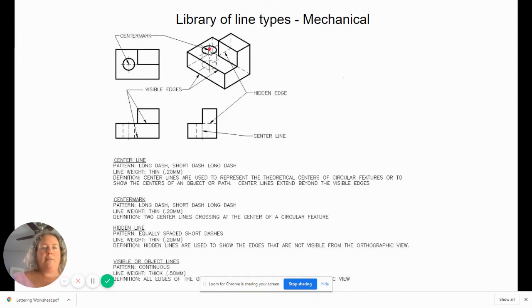And then you have the center mark indicating where to center that drill. And so we see the side view of that path that the drill would take here and here. And in the top view, we see the bullseye, basically, where do we line that drill up for the part to drill that hole in the precise location. So that's the difference between center line and center mark.